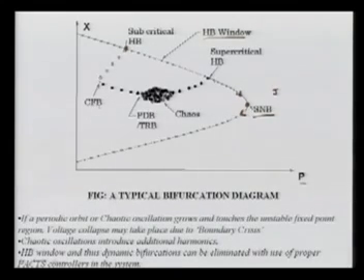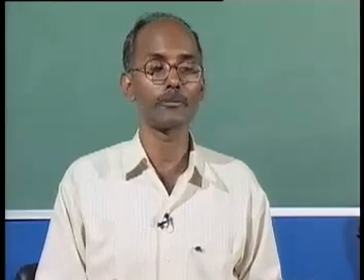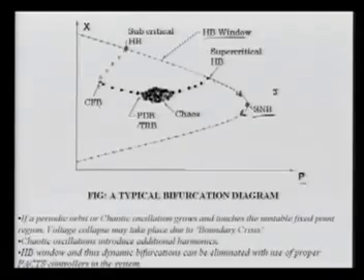So this point is called your cyclic fold bifurcation. It was unstable and now it is folding back, and here it is stable now. Now in the period doubling bifurcation, as I said, it emerges out from the stable. Here this is stable, and now the frequency becomes double, or in the torus it is a fraction. So here the original becomes unstable, and then here it is somewhere, and this point is called the chaos.